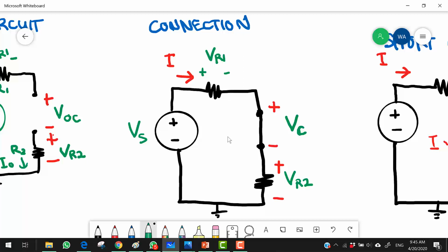And this voltage across the connection here, because we have just connected it, means that the resistance here is 0, right? So even though the current is not 0, voltage C here, because it's just a connection, is going to be 0 volts. So basically what you've done is that you've shorted this connection, but this short simply means it is connected across zero resistance. This short here does not short out any other elements. Okay, so this is just a connection. Now, what if I have a connection that shorts out another element?